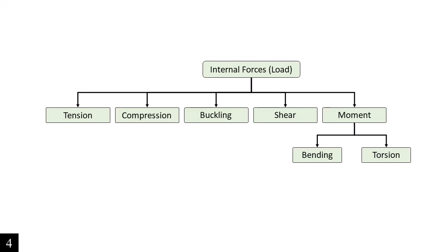Bending failure is different from a shear failure. It will have some warning signs such as a crack, and it has time to develop the failure. So usually this type of failure is less dangerous than the shear failure, because this one will bend down. So you can see the cracking is on the bottom.